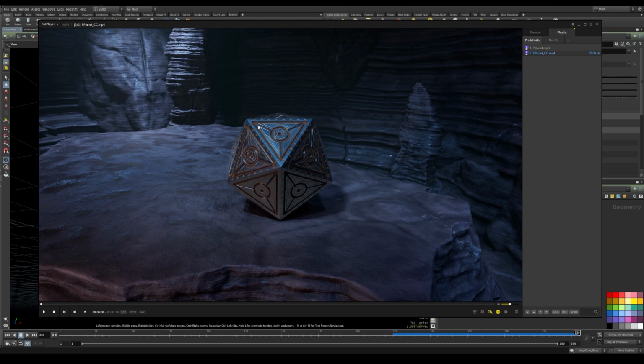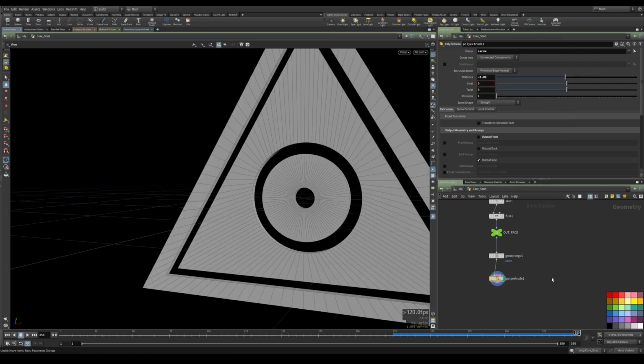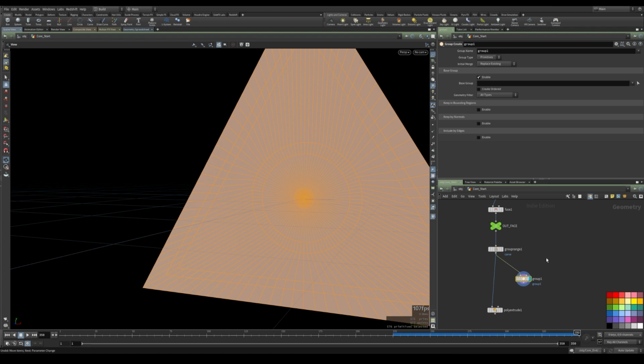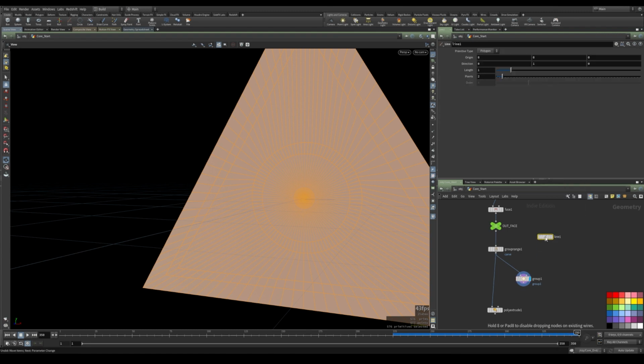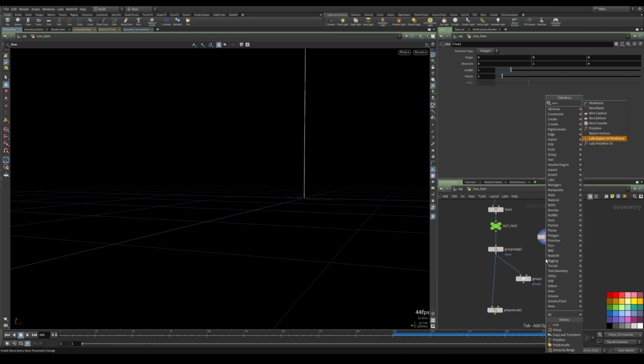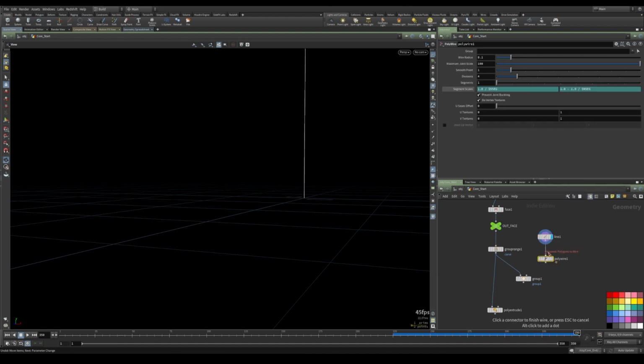But as we see from the reference video, we also have some curving occurring across the face. So to create those other curves, before the actual extrusion, let's create a group node and plug the group range into the left input. Now we want to use a line, just a simple line on the y-axis with a polywire to give it some thickness.